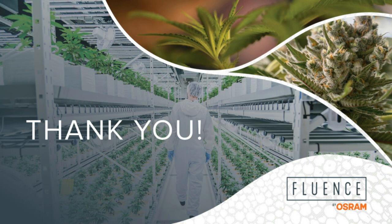Got you. And that's a good question. What we like to see early on in cloning is an elevated root zone temperature to push the plants to make roots. And then once you leave that stage, we taper off the temperature and push it towards a cooler temperature. Anywhere between 75 and 78 is ideal, and then with a higher relative humidity, gradually removing humidity day by day. So I would say around 75 to 78 is ideal for roots and then the transplant phase.